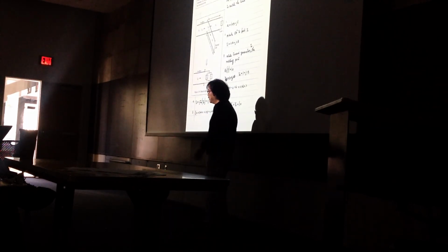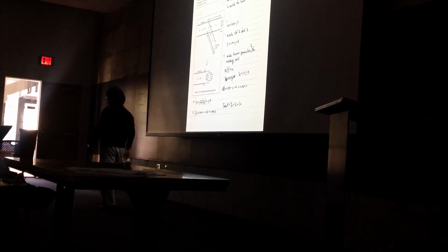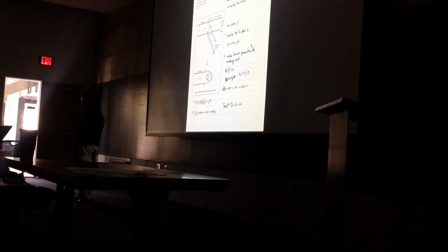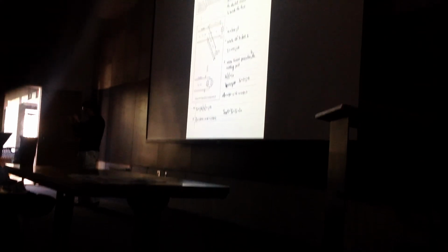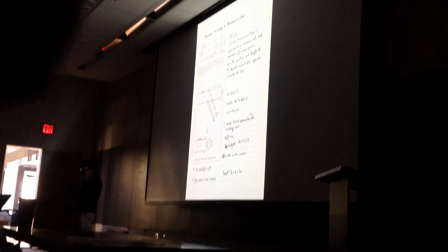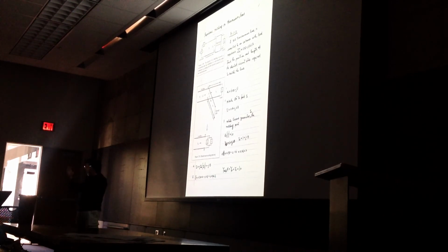So you don't actually have to place an inductor or capacitor into these circuits, you can just use a transmission line of different lengths. That's one way. And doing it this way is better, because you actually have a wider matching. When you are at a different frequency, you're going to have a gamma that is not equal to zero but is small. So you have a better benefit.